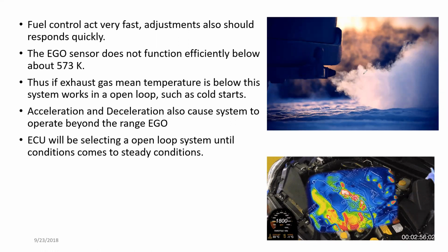In some other cases, like very high accelerations and decelerations, the system can go beyond the exhaust gas oxygen sensor's limit. At that time, the engine could sometimes give a trouble code, or a check engine light in a vehicle with trouble codes. In such cases, switching the engine off and on will bring it back to normal conditions.